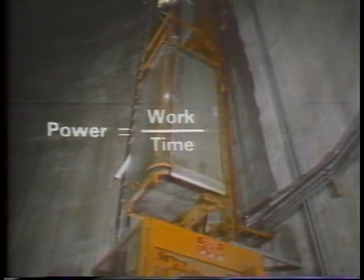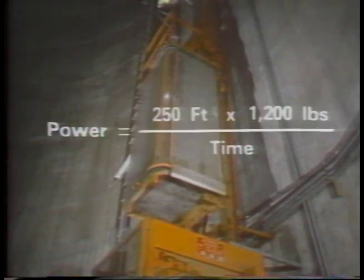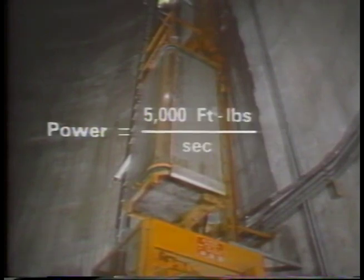Now, since we're talking about work done by the elevator, the equation we'll use is power equals work divided by time. Now, work is equal to distance times force, and in this case, the force is weight. So we have 250 feet times 1,200 pounds, and time is equal to 60 seconds. This gives us about 5,000 foot-pounds per second as the power consumed by the elevator while lifting 1,200 pounds, 250 feet in 60 seconds.